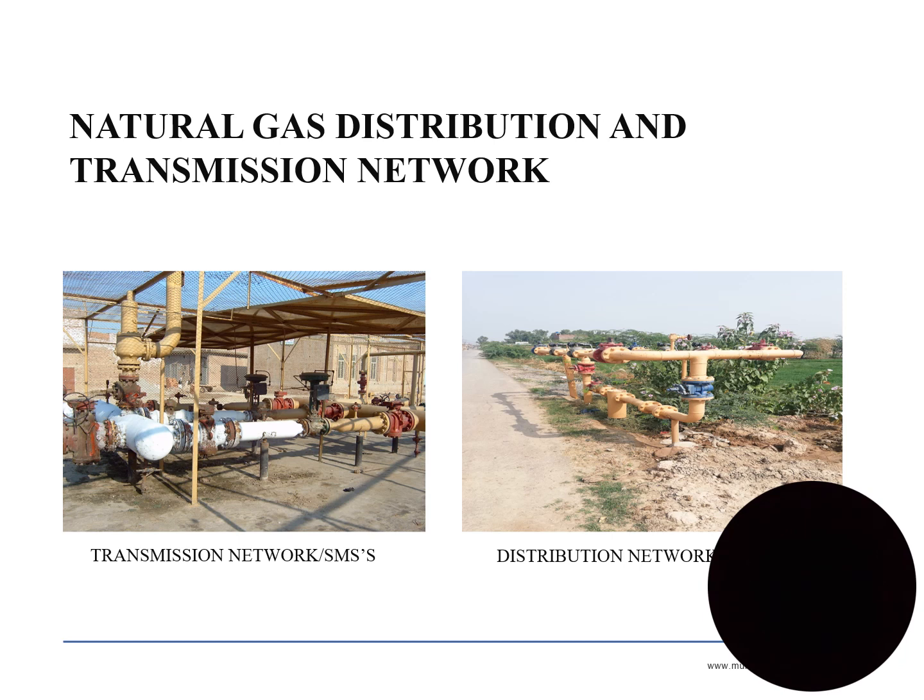By releasing a lot of energy, common structural metals can be extracted from ores or naturally occurring compounds. These metals reach metastable states and frequently lose energy by reverting to essentially identical compounds to their initial state. For instance, hematite can be heated with carbon to create iron, and iron corrodes and transforms into rust to complete its life cycle. Hematite and rust share the same chemical makeup.